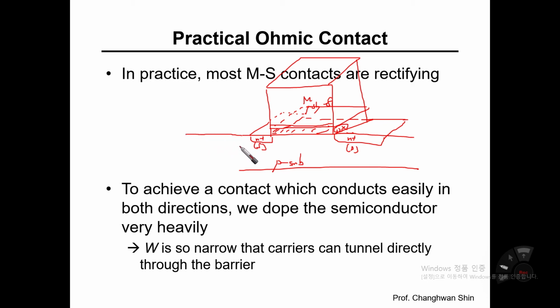Okay, so whenever we say this three-terminal MOSFET, some textbooks introduce that we can take advantage of a fourth terminal named the body. The body indicates that this is a P substrate. Then my question is how to deliver your body voltage to this MOSFET. Can you deposit the metal on the back side of the substrate? No, this is not allowed.